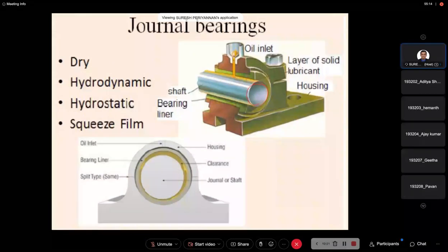Now, are we able to see now? Later we discussed the bearing characteristic number and the bearing modulus. After that we discussed the Reynolds equation. The Reynolds equation, as I just told you, is used to study the hydrodynamic lubrication behavior. Hence, Reynolds derived it in the form of partial differential equations, right? But that partial differential equation, whatever he developed, did not give the full correct analytical solution.